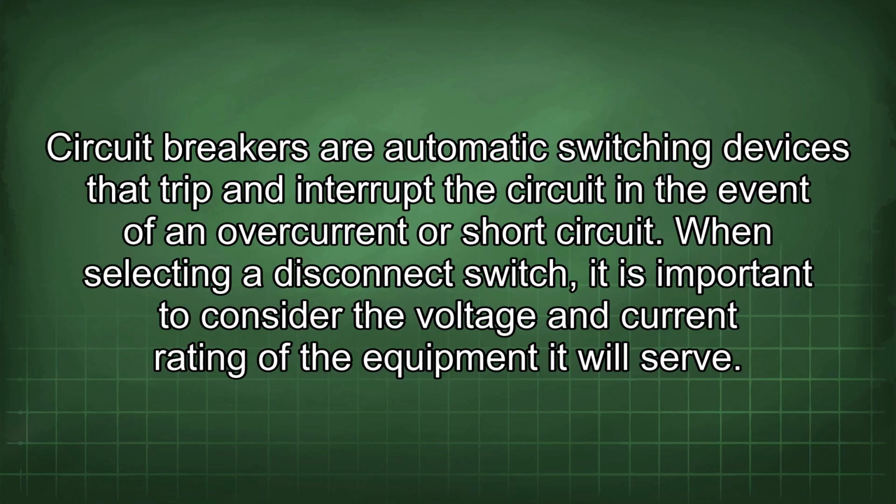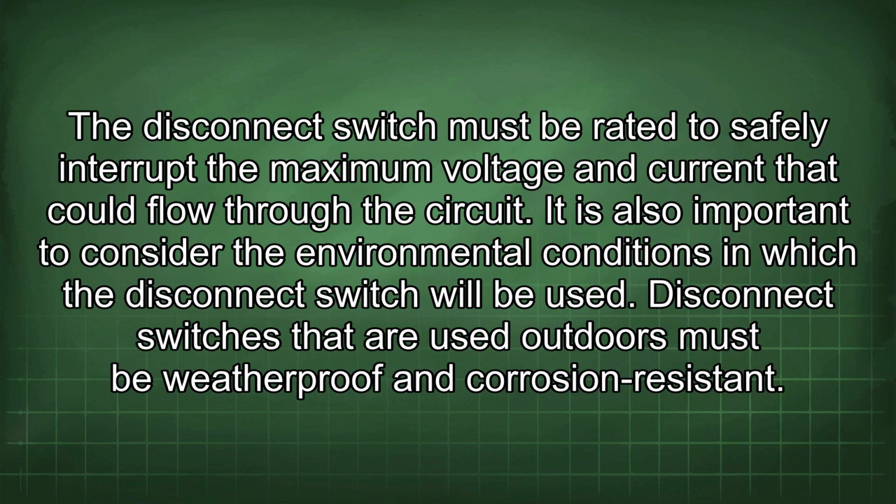will serve. The disconnect switch must be rated to safely interrupt the maximum voltage and current that could flow through the circuit. It is also important to consider the environmental conditions in which the disconnect switch will be used. Disconnect switches that are used outdoors must be weatherproof and corrosion resistant.